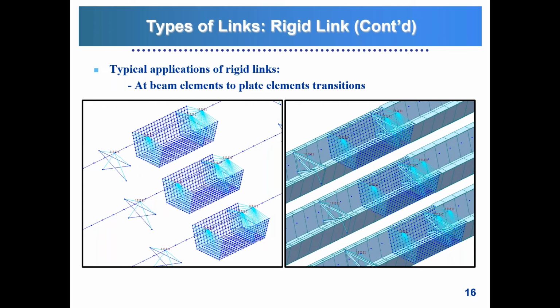The capacity of the bottom flange was insufficient, and it was buckling because of that negative moment, or compression on the bottom flange rather, due to that negative moment.